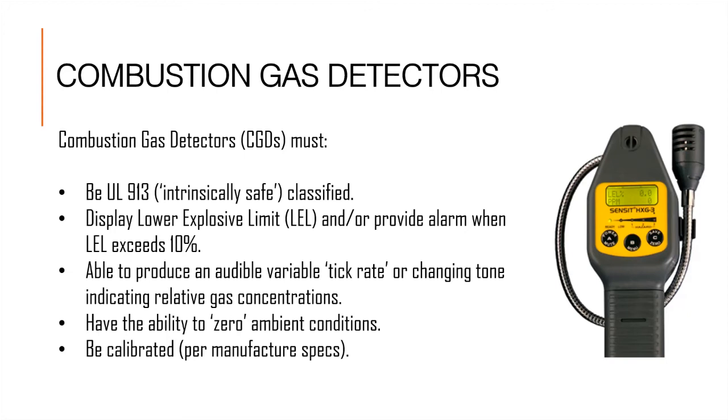They got to be able to produce an audible tick rate that can change, and it speeds up as it begins to detect more concentrations. And then, of course, it has to be able to zero out when it's outside. Obviously, it should be calibrated to be current with its manufacturer's specifications.